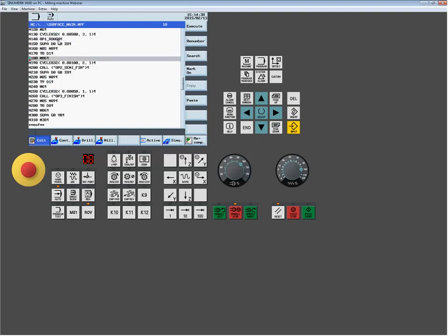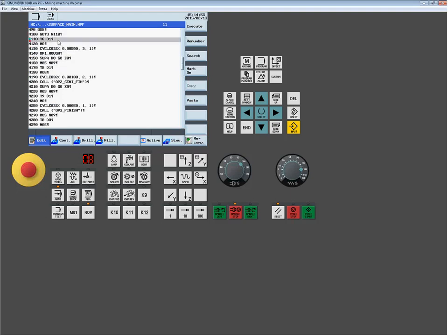Further down, I change tools again. In this case, I'm using the same tool. I repeated the tool change statement. It's redundant, but when I'm bouncing around, it allows me to bounce a little further down the program. So I can jump over this tool, but still force a tool change down here if I wanted to maybe just jump over to the semi-finishing operation.